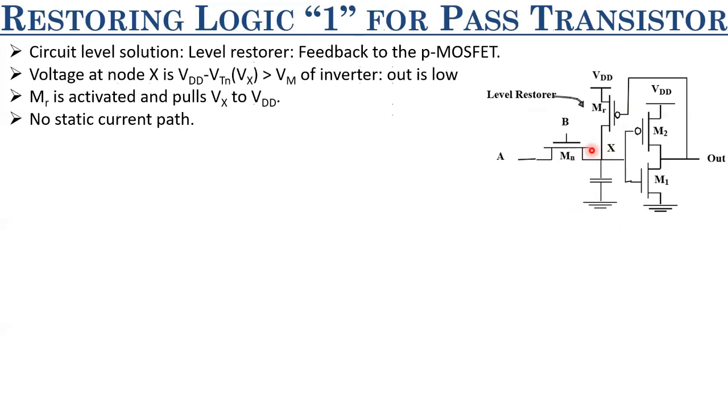I won't say it's zero, because there would be subthreshold leakage current and static power dissipation would be finite and significant. But as compared to the previous circuits, like when you had pure resistors as load, or even the pseudo NMOS logic, there is no static path here for currents to flow between VDD and ground, and as such, static power dissipation is minimal.